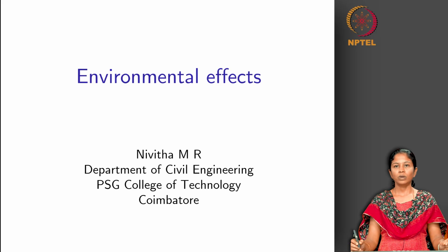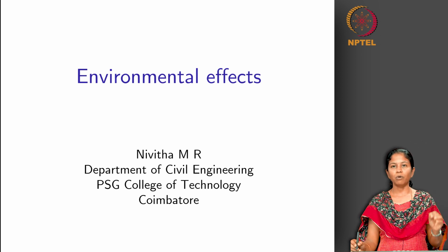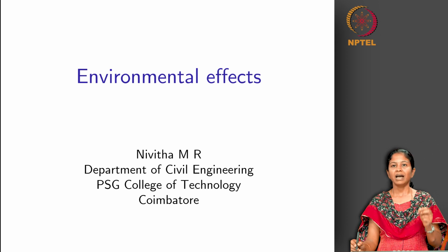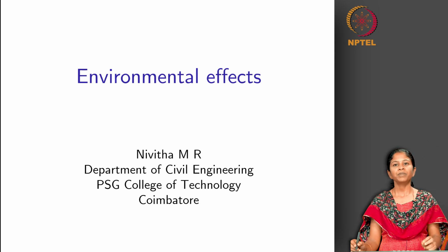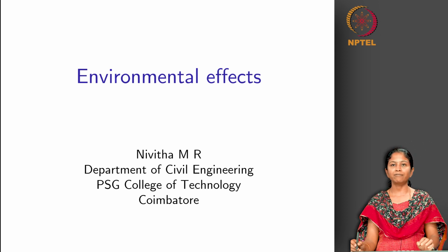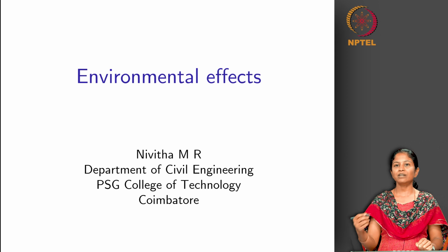Hello everyone, welcome back. In this lecture, we are going to start talking about the effect of environmental effects on the performance of the bituminous pavement, right. So far we were only talking about the modulus, the measurement of modulus for different layers. So now we are going to see how the environmental effects affect those modulus parameters, to what degree these modulus parameters vary depending upon the environmental effects, because ultimately if there is a variation in modulus for a given stress condition, the strain is going to vary.